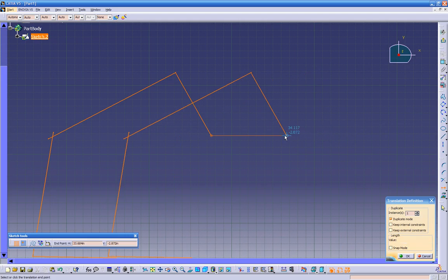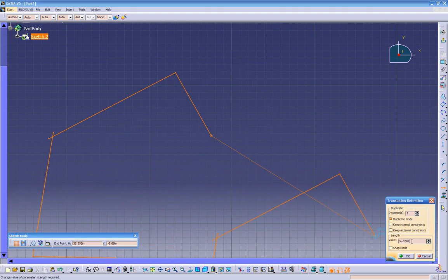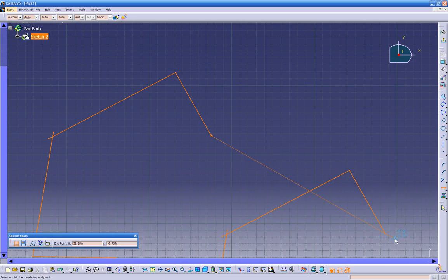to this point. And if you have a dimension you want to move it to, before you drop it, you just click the tab key. Oh, it seems like it's going over here. So let's hit this value over here. So let's say I want to move it 10 inches. So let's type 10, then enter, and watch this.